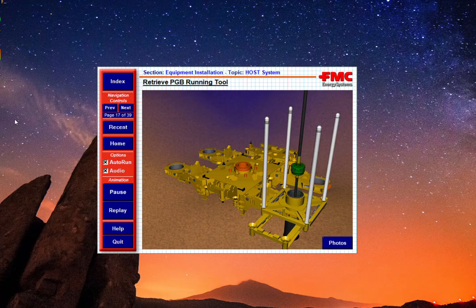The 30-inch cam actuated tool is released by rotating the drill pipe approximately 3.5 turns to the right and picking straight up. The 18 3/4-inch UWD-15 high-pressure wellhead housing is made up onto the 20 by 16 or 13 3/8-inch casing strings at the surface. The assembly is lowered to the sea floor by an 18 3/4-inch cam actuated running tool that is attached to the drill pipe. Just to mention it quickly, how this wellhead locks into the starter head is extremely important